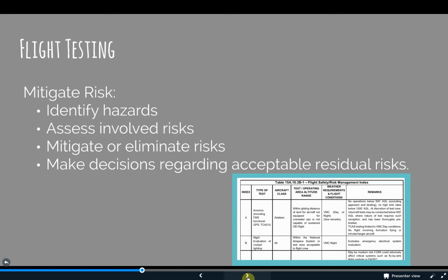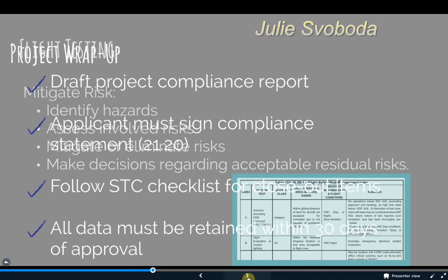As described in Order 8110.4, risk assessment is normally done by a safety review process where project and non-project personnel review a flight test plan. This determines potential hazards and recommended mitigating or minimizing procedures. Both the flight test pilot and the POA agree on the risk assessments, which is shown when the pilot concurs and the POA signs the TIA. For medium and high-risk tests, the FAA must be coordinated with to see if they'd like to participate in the Safety Review Board and to get their concurrence on the risk level defined.